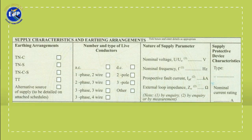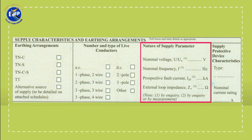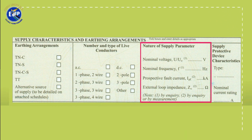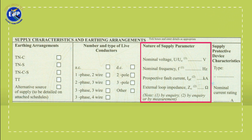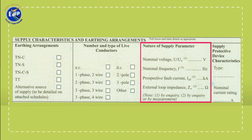Under the nature of supply parameters, you are required to indicate the nominal voltage. The nominal voltage in Ghana today for a single phase is 230 volts, and for a 3 phase is 400 volts. You are also required to indicate the supply frequency. Our frequency in Ghana is 50 Hz, so you write that accordingly.